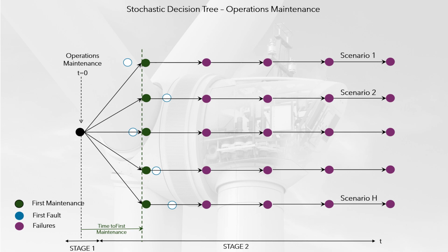Rational is a decision that implies that the first maintenance is done somewhere in the middle of the range. There will be potential scenarios in which the useful life of the asset is lost, and the opportunity cost is paid for not using it. And there will be potential scenarios where the asset, or component, fails and the cost of failure is paid. The decision of what is best depends on the value of the costs associated with the maintenance and failure of the asset.